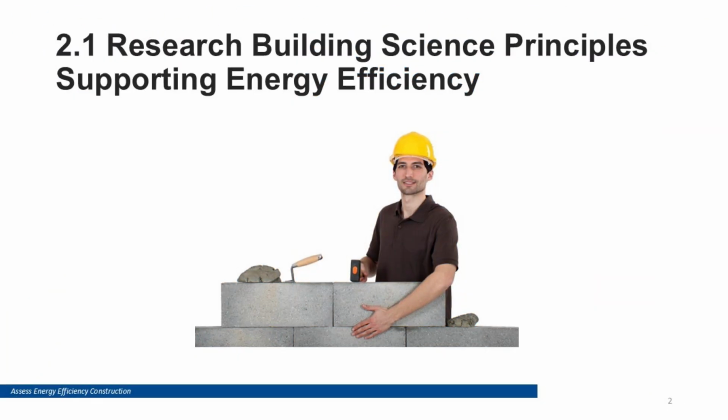Research building science principles supporting energy efficiency. Four building science concepts guide energy efficient construction: heat flow, air flow, moisture flow, solar radiation. They interact, so improvements in one area can create new requirements in another, especially around air tightness, ventilation, and moisture control.